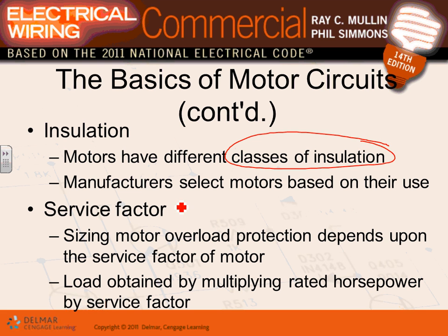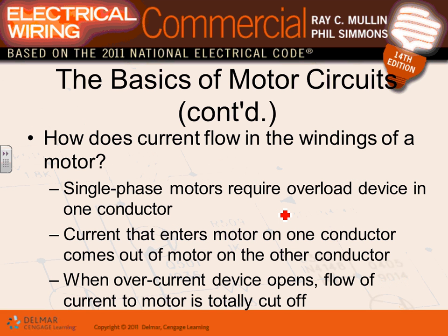And there's also service factor. Service factor is a multiplier that you multiply by the horsepower to give you the extra horsepower that the motor can deliver. So if your service factor is 1.15 and your motor is a 100 horsepower motor, this means the motor is capable of delivering 15 horsepower more than what it's rated for, to handle the inrush, or to handle more load on that motor. So that's your service factor, and it has to do with sizing overloads and so forth. So we talked about the service factor and insulation.